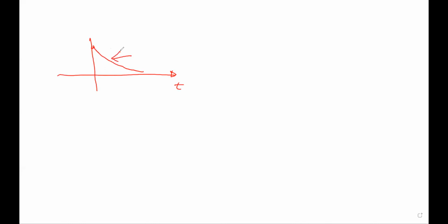So this is the equation, okay? That equation is equal to E R2 divided by R1 plus R2 times e to the power minus t divided by R2C, for t greater than or equal to 0, isn't it?